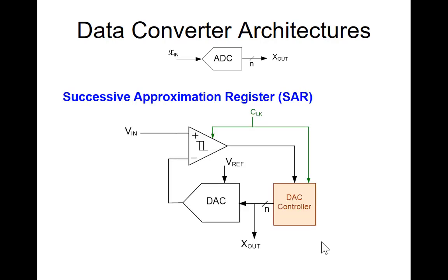And here's a SAR ADC, successive approximation register. It only has one comparator, and it has a DAC. What we do is we guess an input to the DAC, compare it with the input, and see what the output is. If we guess often enough, we can see that comparator output change between 2 successive Boolean inputs.